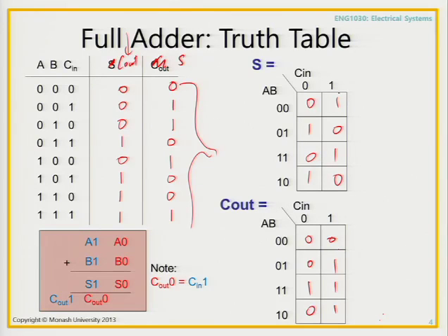Okay, so what is this? What are the rectangles of biggest size in this table? 2 by 1. Where's a 2 by 1? I can go from this corner down to this corner, or this corner around to this corner, but I cannot just go from this corner to this corner. Even Pac-Man can't do that one. Okay, so good. I hope I cleared someone's understanding of the wraparound effect, which is the purpose of this. Okay, so I've only got ones here, so that's not ideal, but it happens sometimes.